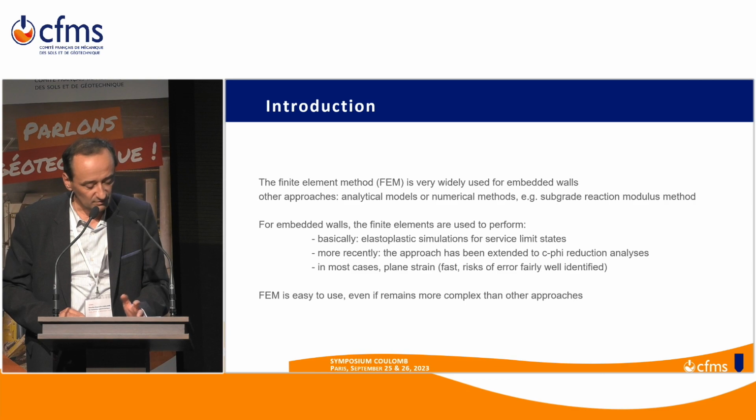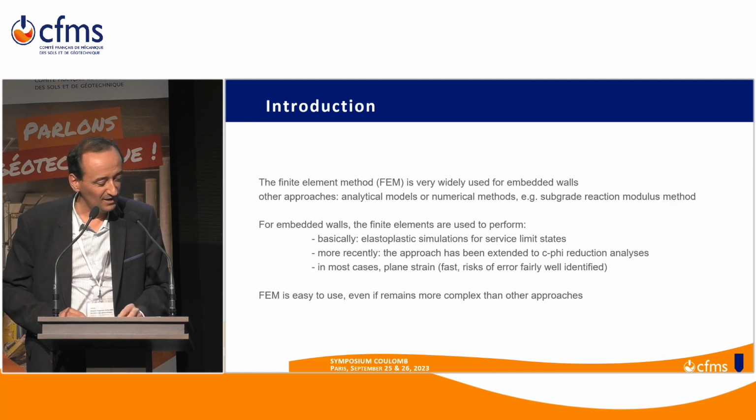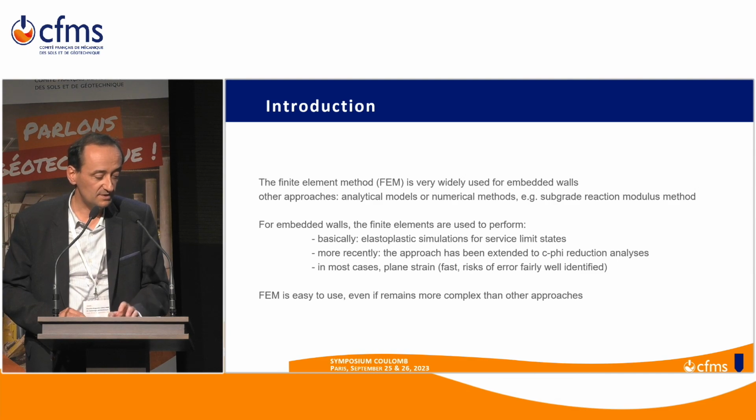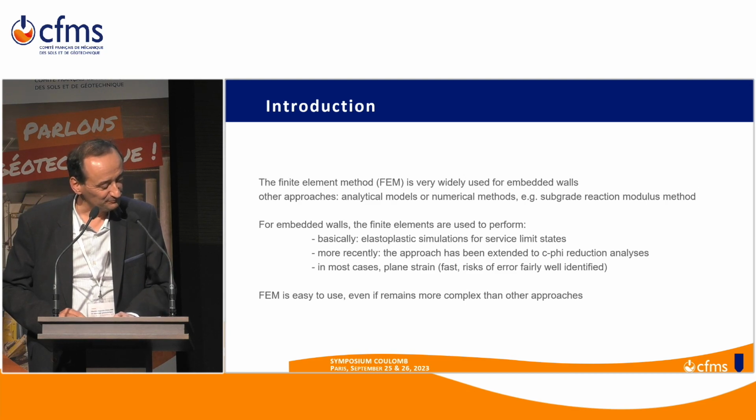Basically, for embedded walls, the method is used for elastoplastic simulations. I didn't even mention that it's in statics. And for service limit states, basically, even if now there is a trend to extend the approach to stability analysis, computation of safety factors, but this is a rather recent evolution due to the evolution of design rules, actually.